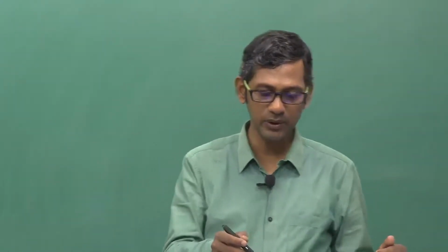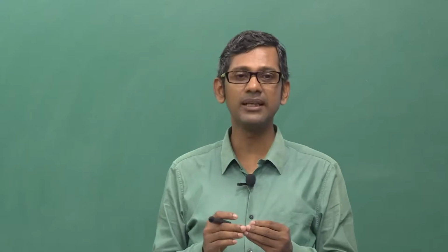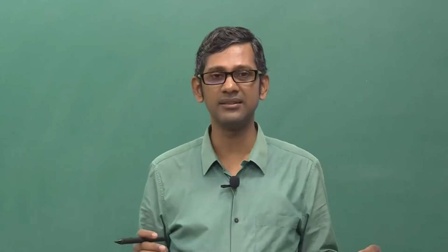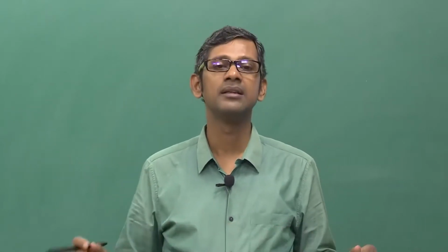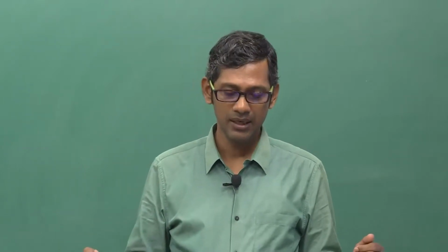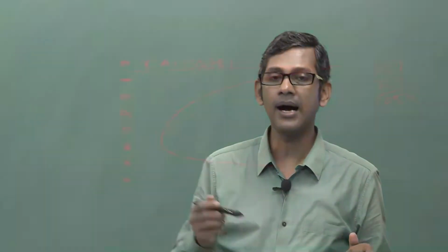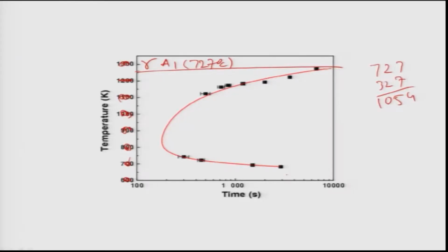At low temperature undercooling is high, that means when you cool it down to a very low temperature, undercooling is very high. Therefore nucleation and growth both can happen easily, but diffusion is slow. So the pearlitic lamellae will be thinner in size, but the number will be high because undercooling is high and nucleation rate is high.